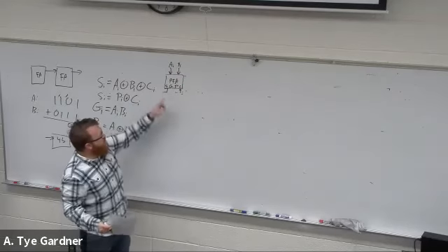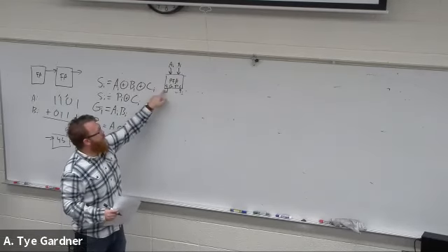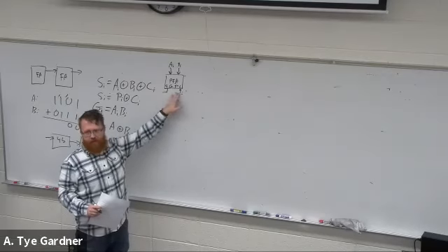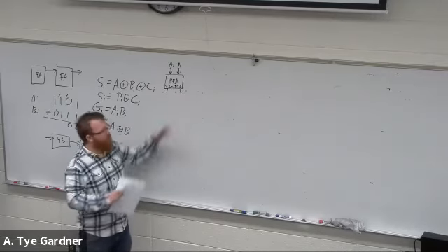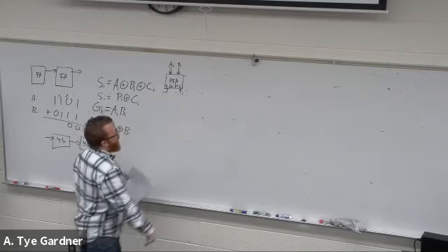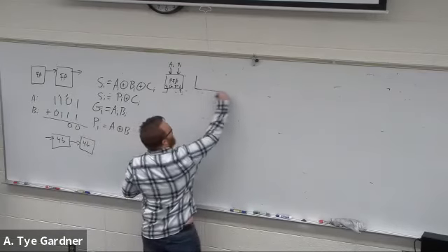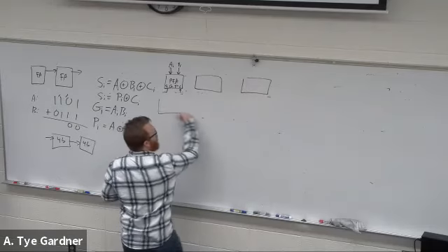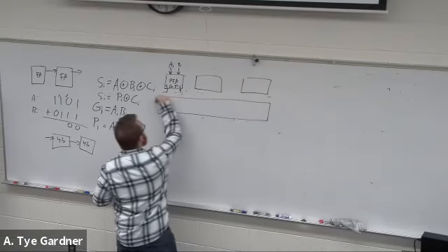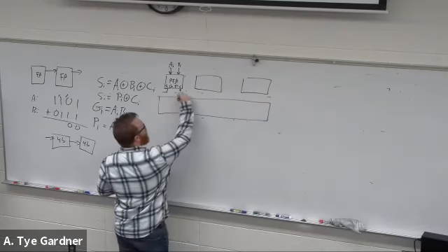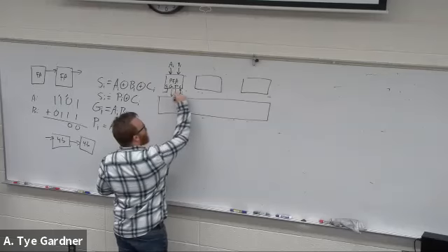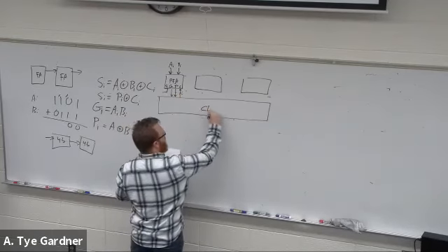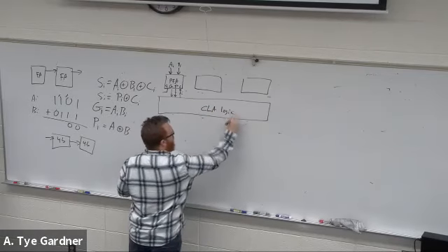So those two plug in, it throws out the sum, the generate, and the propagate, but it needs to consider its carry in. Now there's a reason I put this carry in down on the bottom and put the input arrow, and that's because if I want to start stringing these guys together, this guy is what we'll call the CLA logic.